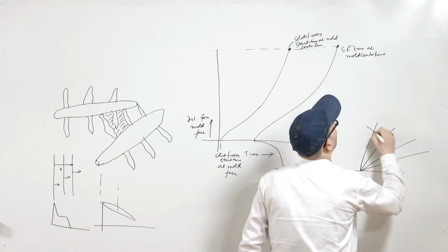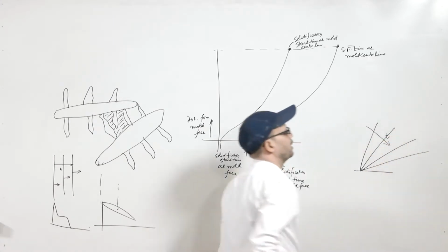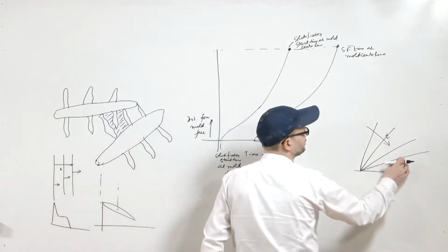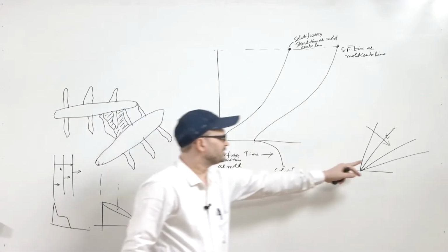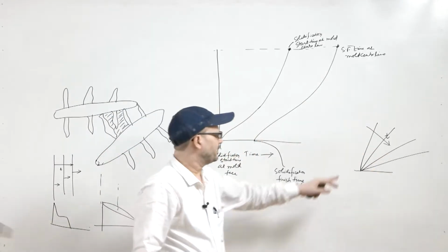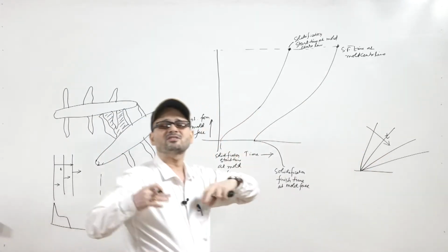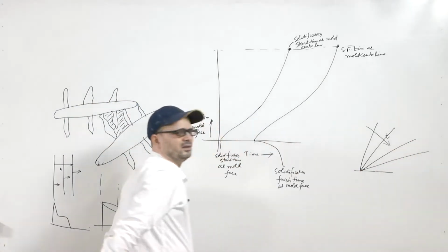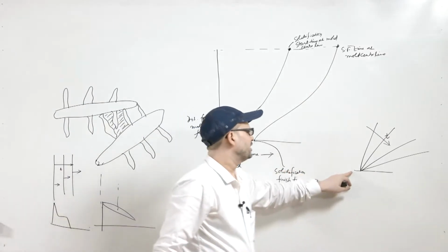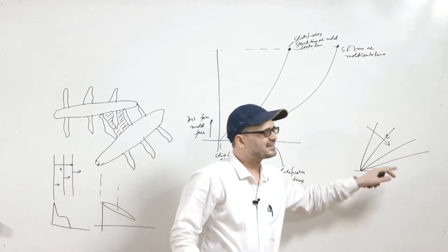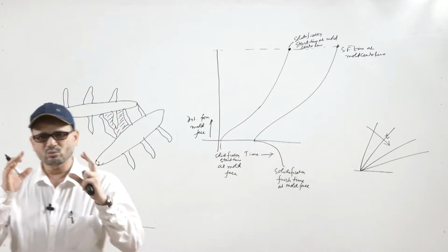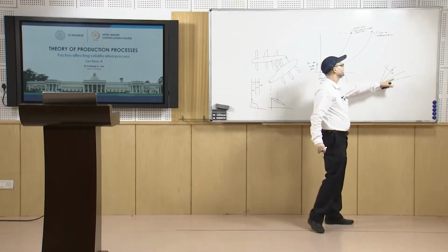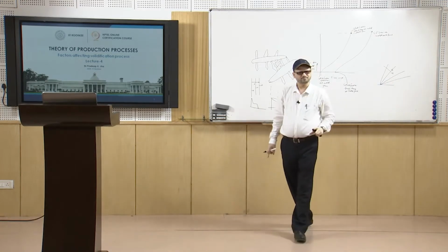As time progresses, the gradient line becomes less and less steep. When it is steeper, you have the chances of plane front solidification, whereas when the thermal gradient line is getting less steep towards the central zone, there are chances of an equiaxed dendritic kind of structure.